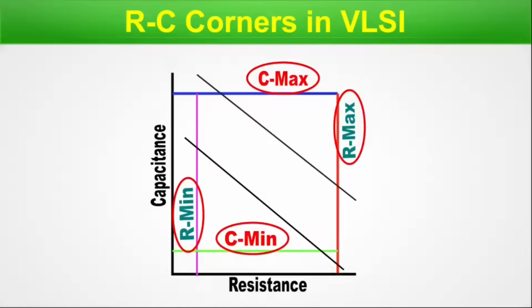Now, where are all these things coming from? These will come from the PDK. I'll come to which file format you will get; I'll come to that point. And these are the boundary limits of the maximum and minimum for both the capacitance and resistance. Now, I'm again emphasizing these are parasitic resistance and parasitic capacitance, not the design resistance or design capacitance. Those are used for the functioning of the design. These are extra, and these are coming from the fabrication process.